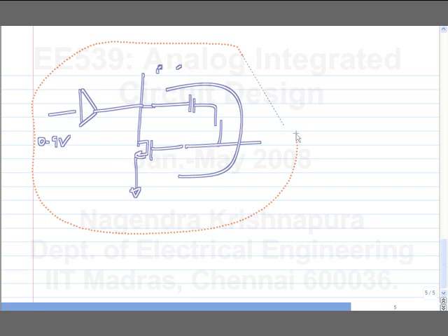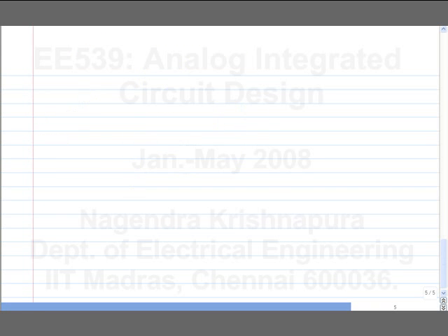So this is also why you need to understand feedback circuits very well, right? So it will come everywhere, even in bias circuits. Of course, we make op-amps with the intention of using it as amplifiers, but you will have it everywhere. Maybe simpler bias circuits, maybe the speed of this is not so important. I don't think you really go and optimize it for the best unity gain frequency. But at least you should be able to design it stably enough.